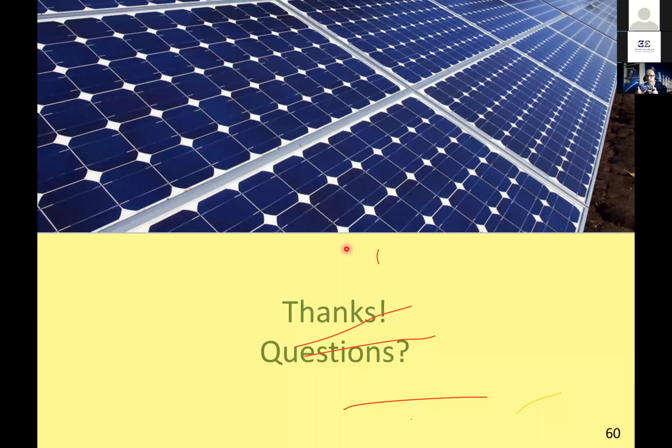But imagine you have a PV panel giving 600 volts and the DC bus is 380 volts. In this case, you can use a buck converter, and you must use a buck converter. If you use a boost converter, it will not work. Okay? Thank you. You're welcome.